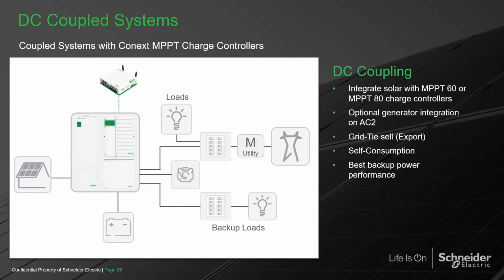Now, let's say the customer is connected to the grid, second scenario, but this customer doesn't have a net metering agreement, doesn't have a bidirectional meter, so is not allowed to export power to the grid. Same scenario, the inverter takes the power from the array and then supports the loads here in the backup panel. In that scenario, these loads are only supported with the grid. Okay, the inverter is connected to the grid in parallel, and all it's doing is providing current here. In this scenario with the grid present, the grid is providing the voltage and the frequency.